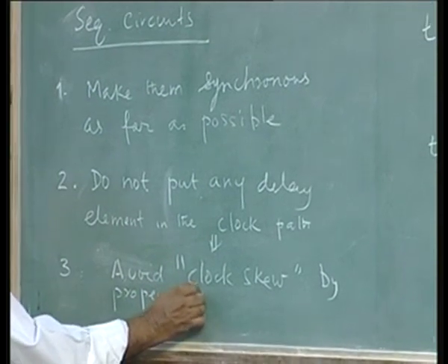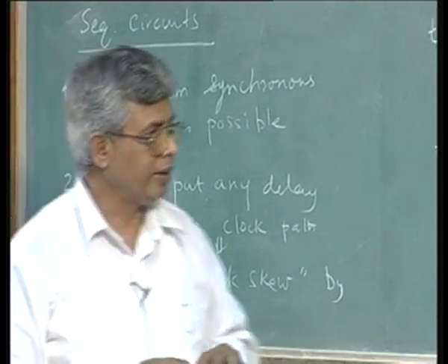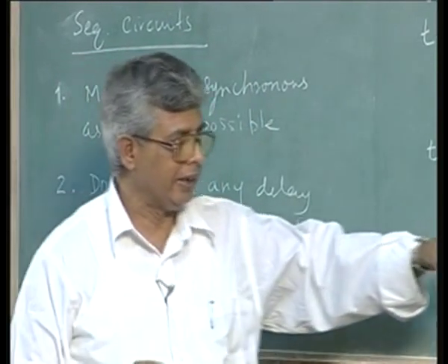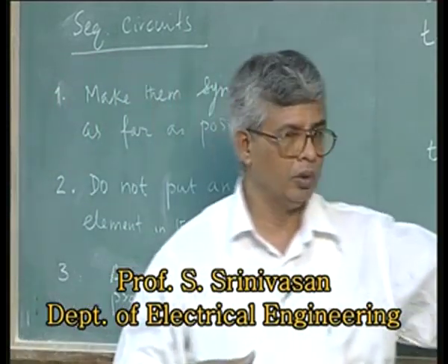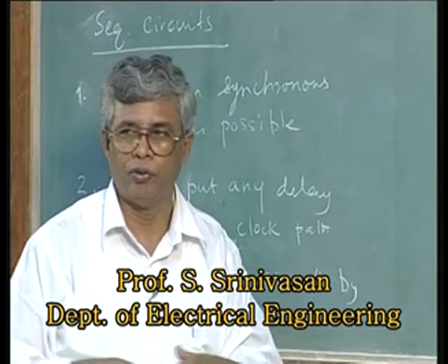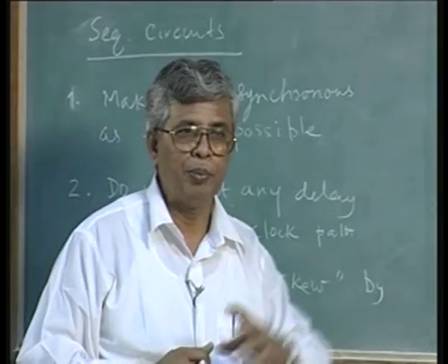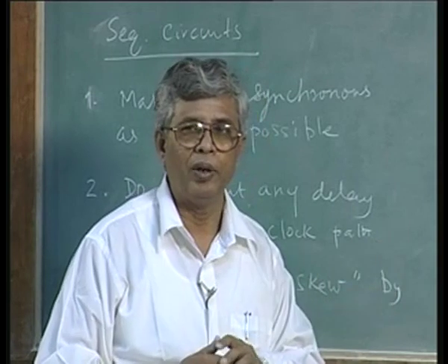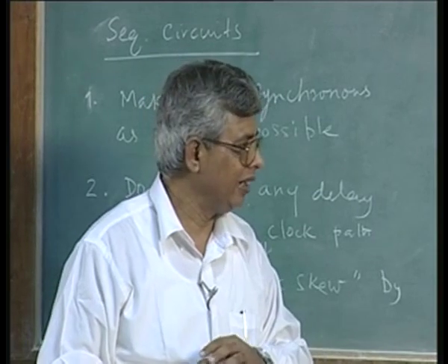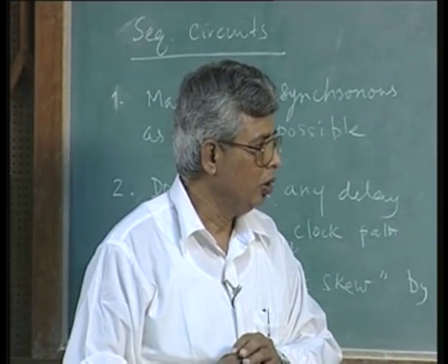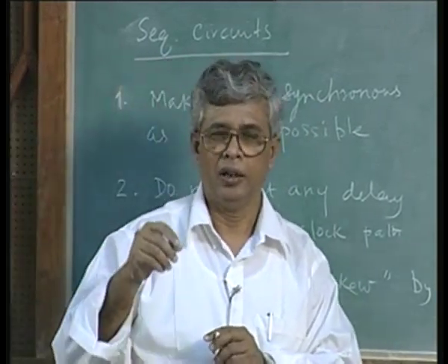So, what we will do next is, of course, these are the rules we will follow in all our designs, and what I am going to do next is to give you certain cases in which, as I started with, we cannot afford to have this series of flip flops in a big circuit. This is going to consume a lot of real estate and a lot of power. So, is there a simpler scheme of getting a flip flop implemented in an IC? In my next lecture, we will talk about some flip flop implementation schemes adapted in integrated circuit design.